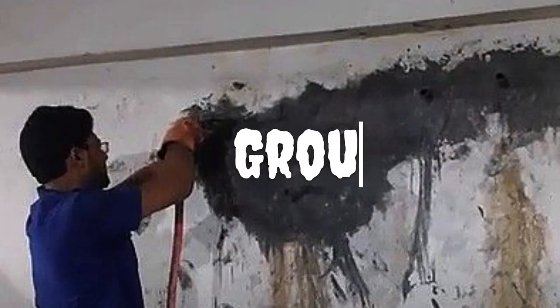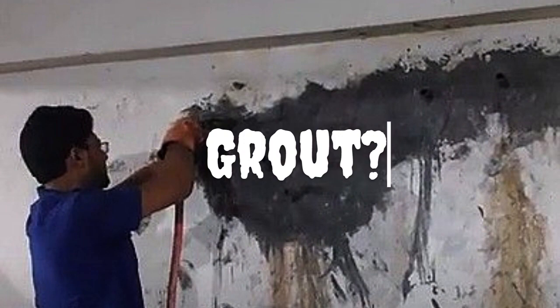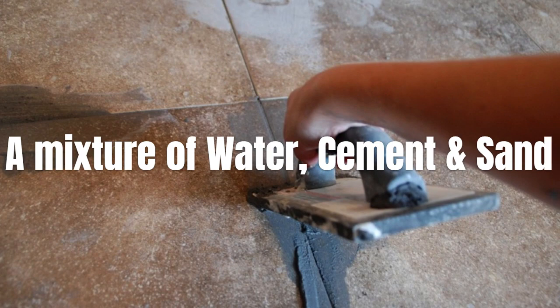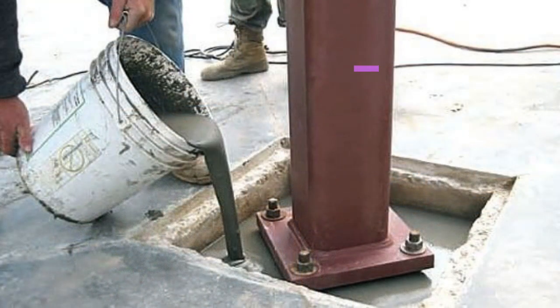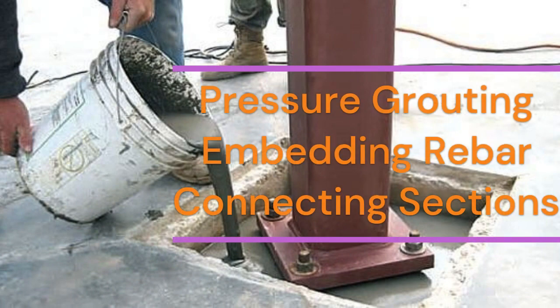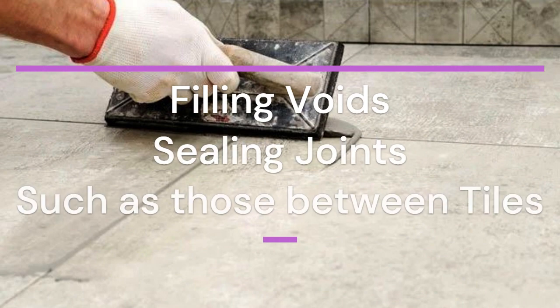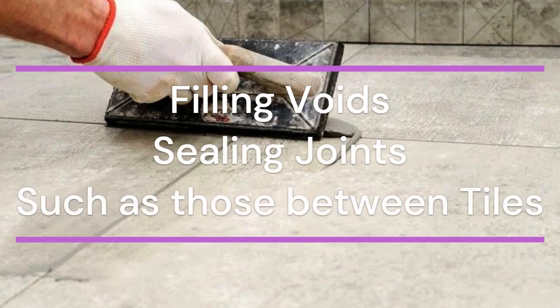Question 3. In construction, what is grout and why is it used? Answer. Grout is generally a mixture of water, cement, and sand and is employed in pressure grouting, embedding rebar in masonry walls, connecting sections of precast concrete, filling voids, and sealing joints such as those between tiles.